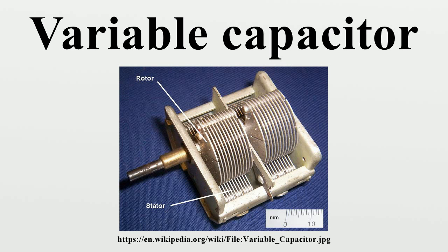The sections can have identical or different nominal capacitances, e.g., 2 times 330 picofarads for AM filter and oscillator, plus 3 times 45 picofarads for 2 filters and an oscillator in the FM section of the same receiver. Capacitors with multiple sections often include trimmer capacitors in parallel to the variable sections, used to adjust all tuned circuits to the same frequency.